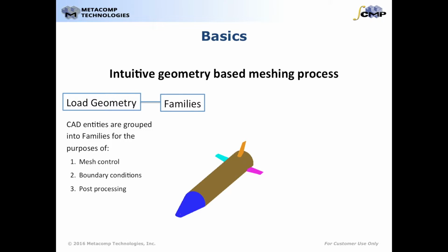Each of the families defined in IMIME will become available to the user in the solver for the use of defining boundary conditions. And finally, users may wish to group CAD entities into families for the purposes of post-processing. For example, users may wish to measure forces and moments on regions of the geometry. Those regions can be grouped into families, which will become available as boundary conditions and available for post-processing purposes.